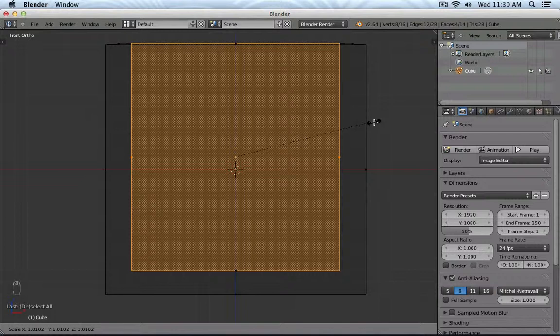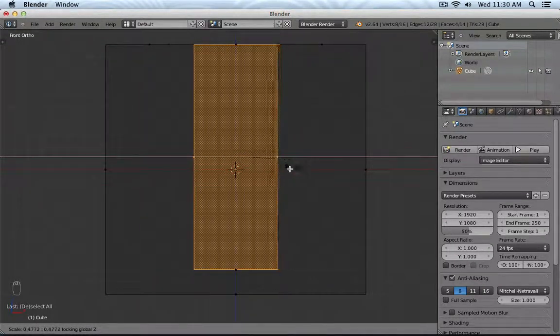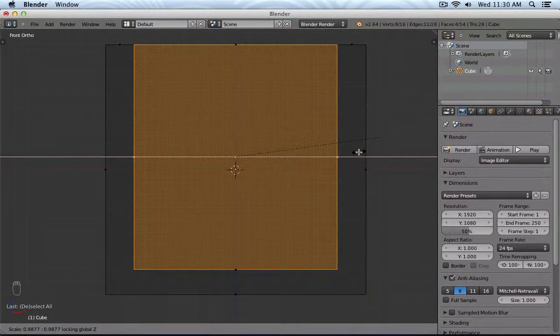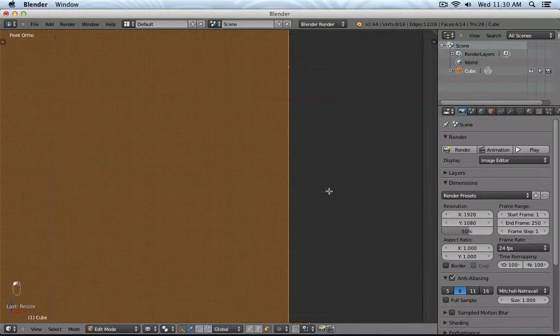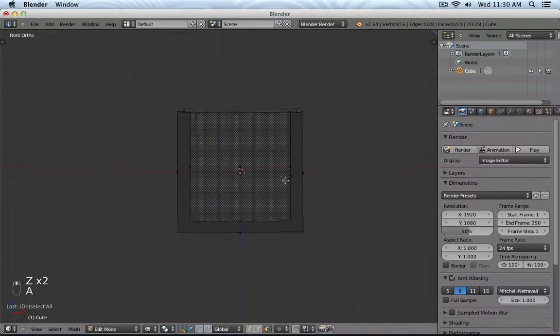And again, to do this, I can press Shift and Z. So now I can only scale along the Y and the X axis. And then I move it roughly to where it should be, somewhere there. And then press, for example, my left mouse button. Can zoom in a little bit, and that actually looks pretty good.